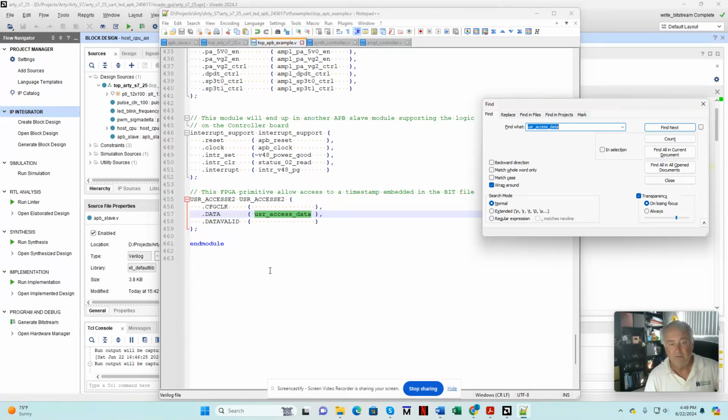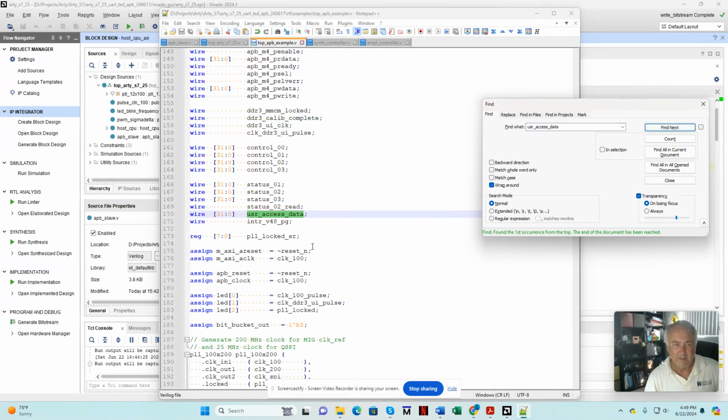And it tells you the date and time that the bit file was generated by Vivado. I use that. Well, it's free, it's easy to use, and I use it all the time just as a sanity check that I'm running the bit file I think I'm running.